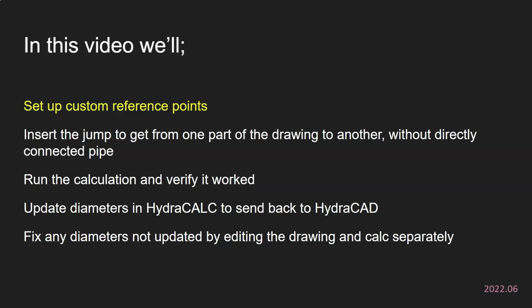In this video, we plan to set up custom reference points. So you'll see me set up some hydraulic reference points where I will be able to recognize them in the calculation. After that, we're going to insert the jump to get from one part of the drawing to another part of the drawing. We will run the calculation and verify everything worked.